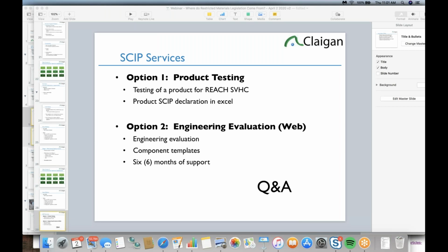Radioactive material is governed under other legislation. Polychlorinated biphenyls are a REACH restriction. Beryllium copper is not restricted at this point in time. Beryllium oxides are category 1 carcinogens, and some of the berylliums end up being regulated under MDR. Beryllium is one of the few materials that classify for regulation but isn't outside of MDR. So beryllium copper is a historical one.